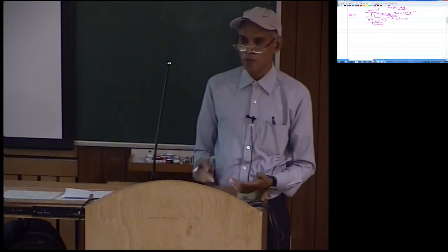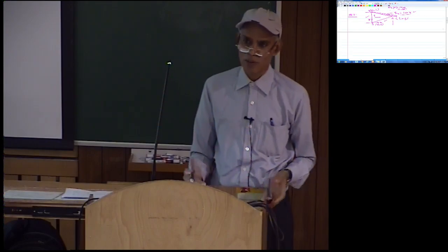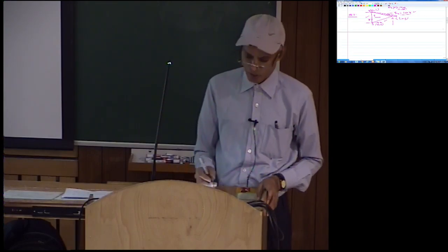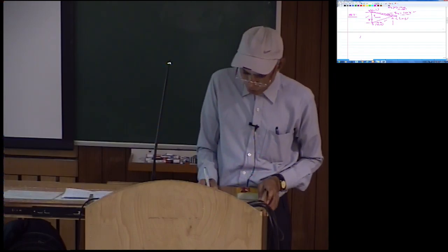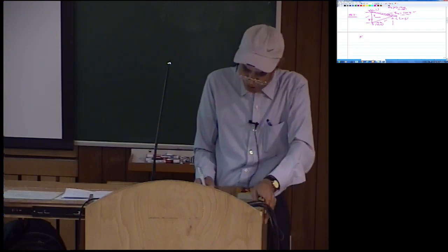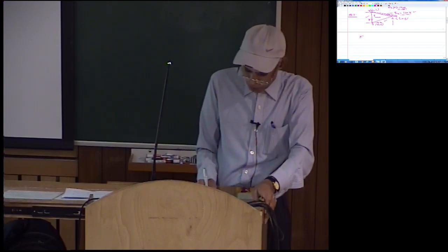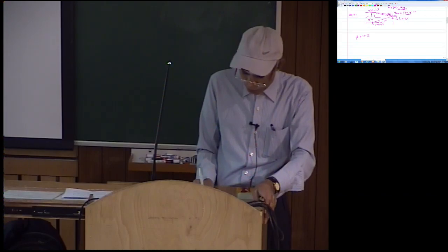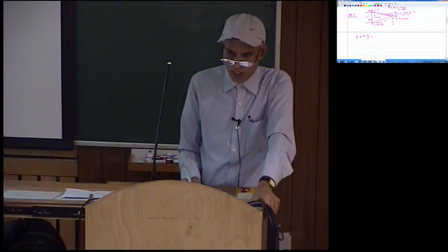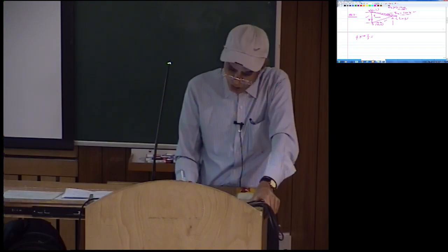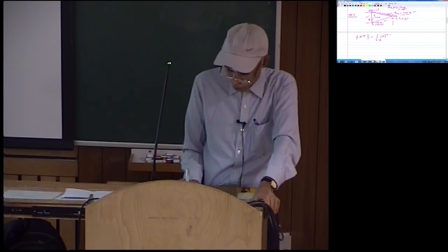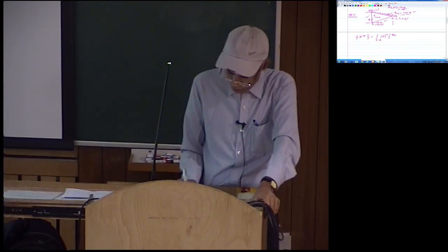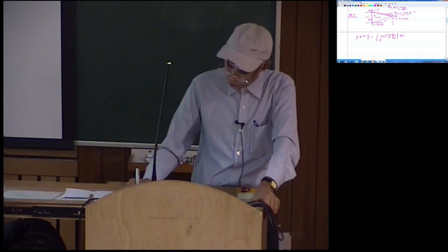We had discussed that, when we use two-dimensional elements, what are the constraints on dimensions and so on. So when you look at that, the only load is this and there was nothing else given. So the load vector, whether you want to call it external or internal, is a known load. The load vector for the element is basically going to be, as we have already done, the integral of H transpose into Q, and the integration is going to be along this edge. So integration along edge 2 to 3 of H transpose, with one force Qx, and in the other direction the load Qy is actually 0, and then ds.